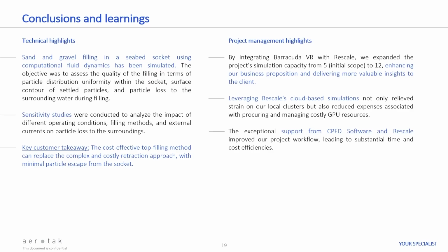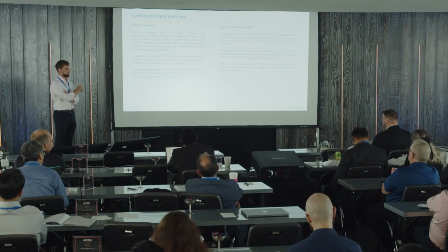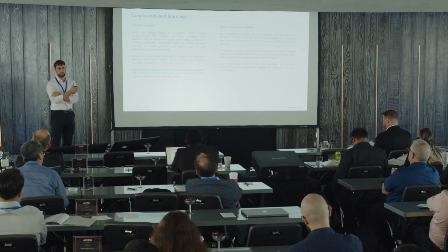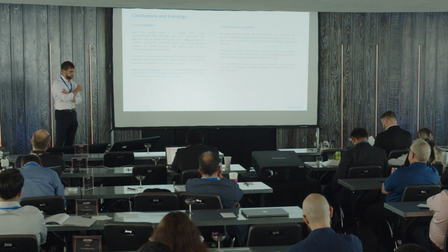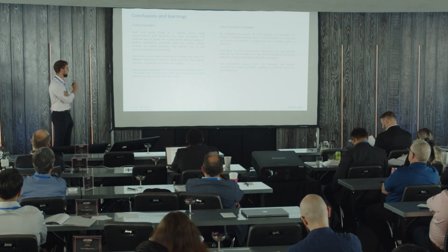The setup that we managed to do, with help from the support team at CPFD Software, allows us to run a number of different sensitivity studies, varying operating conditions and filling methods. We even put an external current on to see how that affected the particle loss. The key customer takeaway was that we can actually do the top filling. It doesn't make worse filling conditions, and it's a lot cheaper for them to do. So they actually ended up going with that top filling approach.